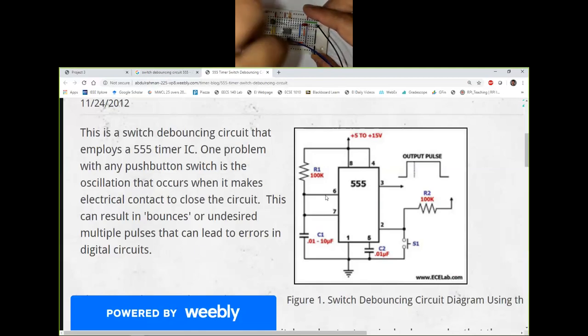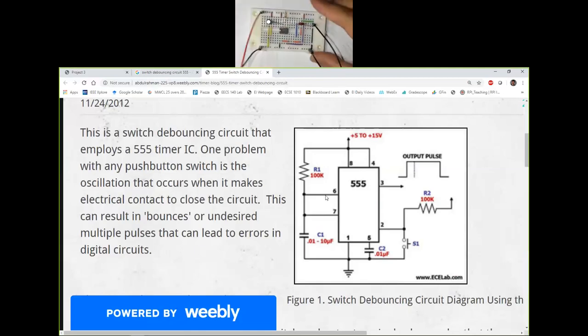I'm also going to remove my orange and blue lines because I'm not ready to measure anything yet. I'm going to leave the orange stripe and blue stripe connected to ground as is. I'm going to bring in a switch, the push button, and I'm going to connect it between pin number 2 and ground. So I have the push button going right there in the middle.